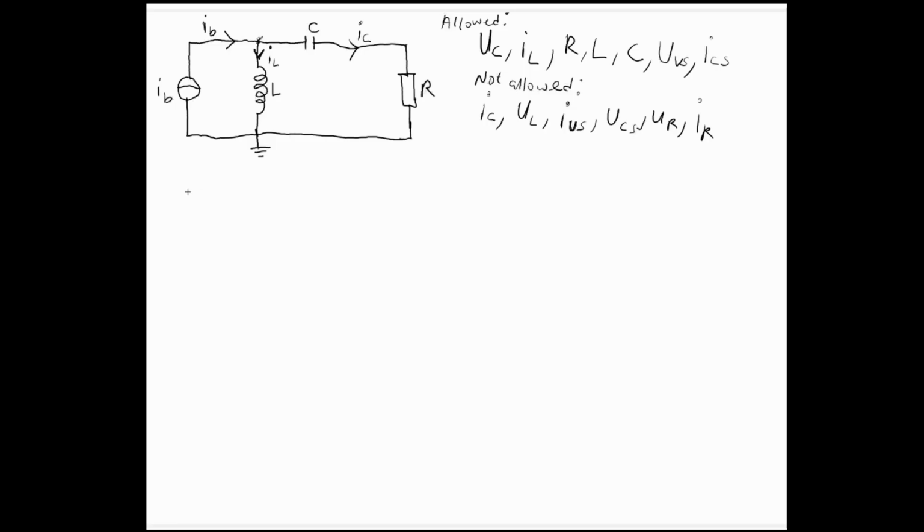Now, the voltage across an inductor is equal to the inductance of that inductor multiplied by the time derivative of the current through the inductor. Having arrived at this equation, the next thing you look at is the left-hand side. Because you have voltage there, and it's the voltage across the inductor, you apply KVL. It makes your life easy because it's voltage. And so you look for the nearest loop or mesh and pick your choice that you want to use to solve it.